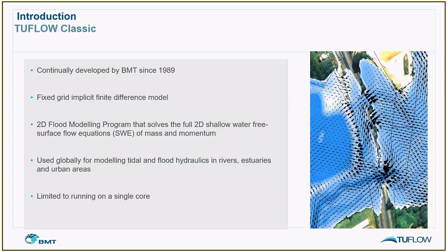So probably the product that we're most well known for is something that's now being rebranded internally TUFLOW Classic. This was first developed in 1989 as a joint venture between BMT and the University of Queensland in Brisbane, and has been continuously developed ever since. TUFLOW Classic is a fixed grid implicit finite difference solution which solves the full 2D shallow water equations of mass and momentum. And since 1989 it's been used throughout the world and been used to simulate hydrodynamics in a large number of urban and estuarine and fluvial environments.